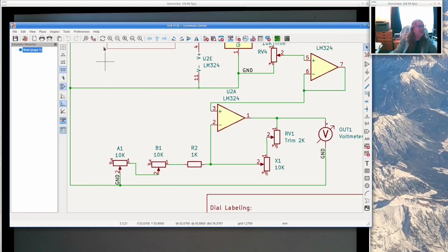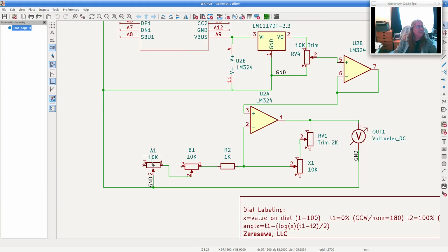Alright, so all of that's just a long-winded way of saying, the way I've got this set up, if A and B, those resistances add up to X, then I should get a 2X multiplier out of this op amp. I got 1.25 volts going in, I should get 2.5 volts going out.